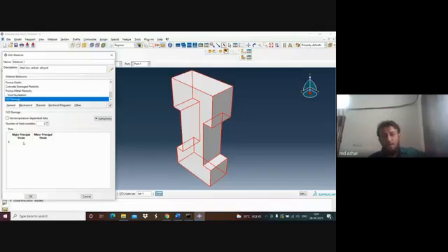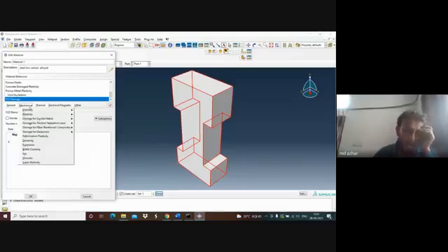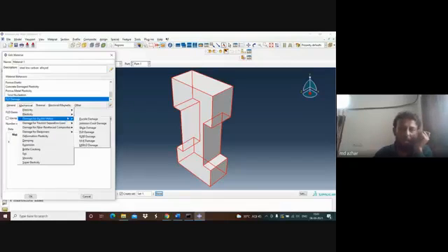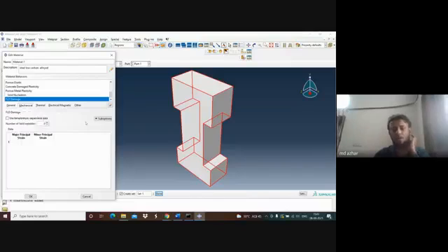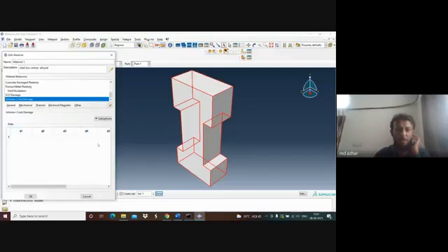Here you have to give the strains, horizontal and vertical strain in any model, which you will get from the 10 experimental values. So these are all part of your mechanical properties. Then you'll have the Johnson Cook damage model. Here you can see different properties are there for the Johnson Cook model, like melting temperature and reference strain rate, which you'll have to calculate experimentally as a part of that material, and then you can put that in.